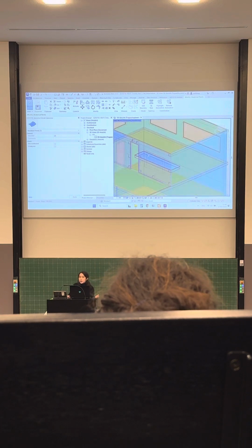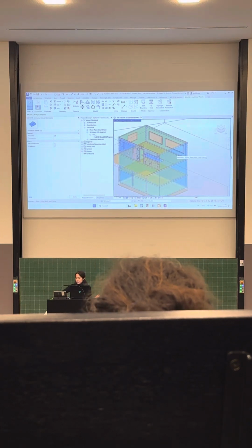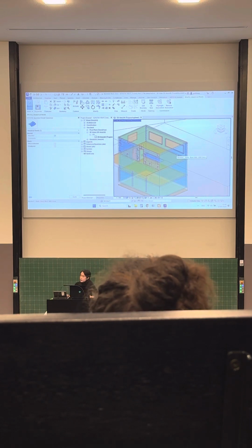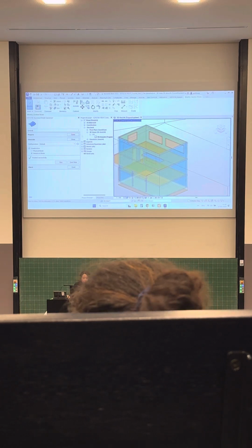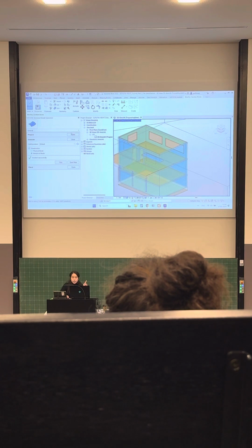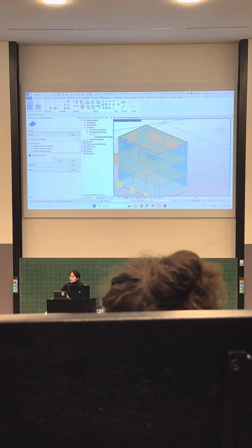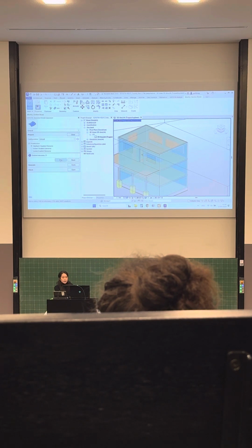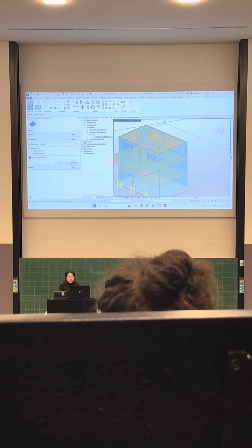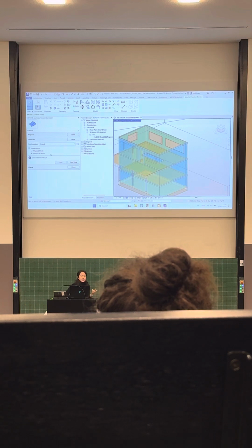Did you manage to get to this point? Problems? Generation or, okay, yeah. It's a bit trickier for me, but I will show you the step. Firstly, you prepare the model, open and run this one. I'm not going to do it because it will do double analytical model for me, but yeah, I'll just talk you through. You go to prepare, you run to see the disabled elements. Then you just go to generate, you choose analytical mode and run it. Yeah, so you will generate the analytical models that you will use later.